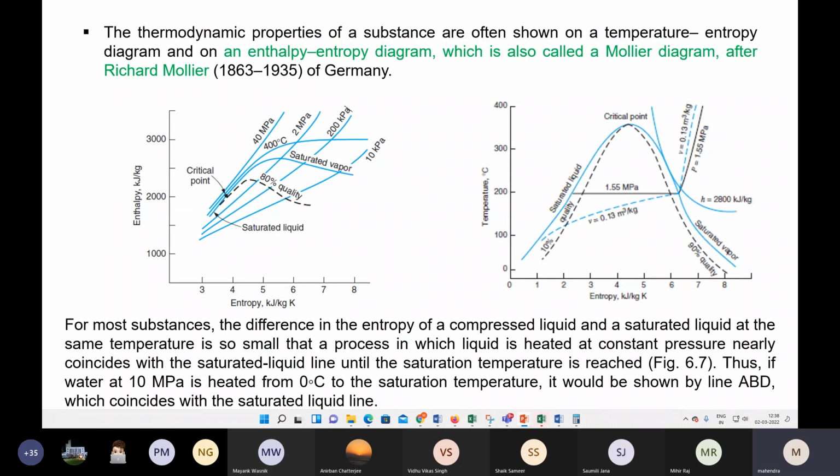And here, once entropy is defined, new kinds of plots you can plot. What plots have we seen? The PV diagram, pressure-volume diagram, we have seen. Then the HT diagram, enthalpy-temperature diagram, you have seen. Then the PT diagram you have seen. Since entropy is a new term defined here, this kind of plot between enthalpy and entropy you can get, and even temperature and entropy.